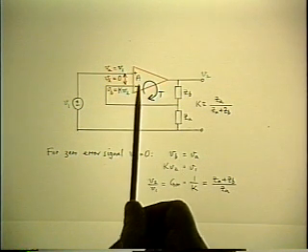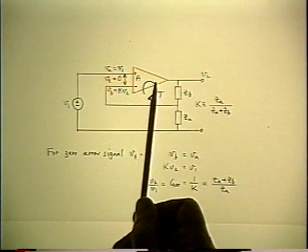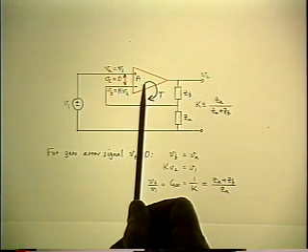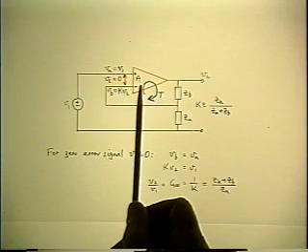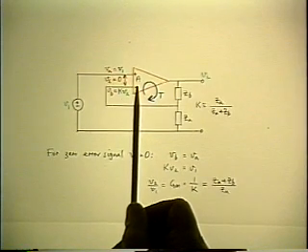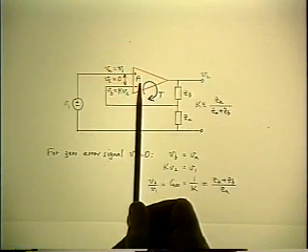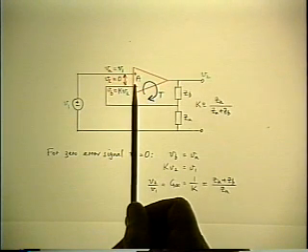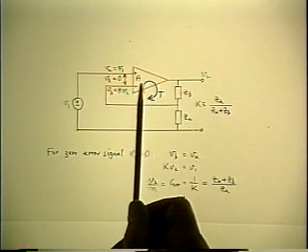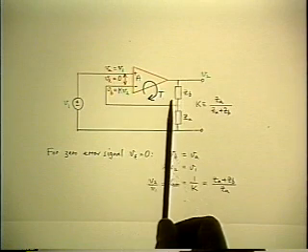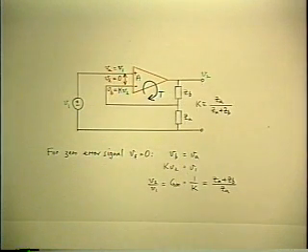Because in actuality, the forward amplifier gain is not infinite. And it may be huge at a very low frequency, but it's also got a low frequency pole in it. Which means at some higher frequency, the gain certainly drops off, and in fact it eventually goes away.